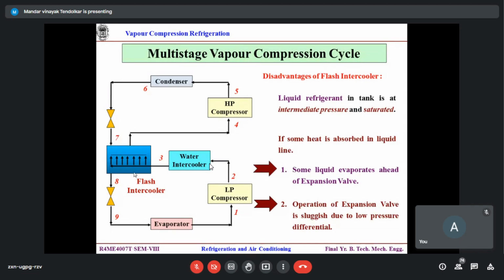So here this entire chamber, I can say, is like an open thing, no? Because it is more towards the phase change part. It's not like one compartment to second compartment, heat transfer, sensible, nothing like that. Entire is the latent part. So if anything happens over here and the liquid absorbs the heat and goes to two phase part, then state 8 will not be a pure liquid.